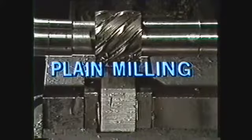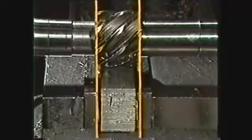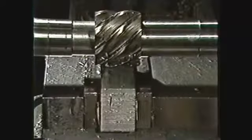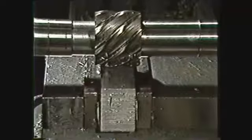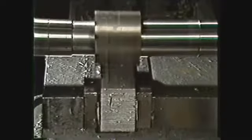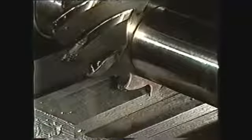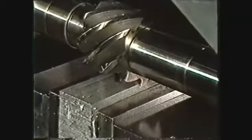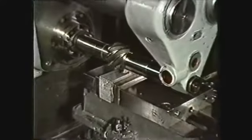Plane milling cutters, sometimes called slab mills, are used to mill plane surfaces where the width of the work is narrower than the cutter. These milling cutters have a helical design to allow more than one tooth to be in contact with the work surface. This kind of cutting action produces less shock and reduces the tendency for chatter. Plane milling cutters do not have side cutting teeth and should never be used in such side cutting operations as milling shoulders or steps on workpieces.